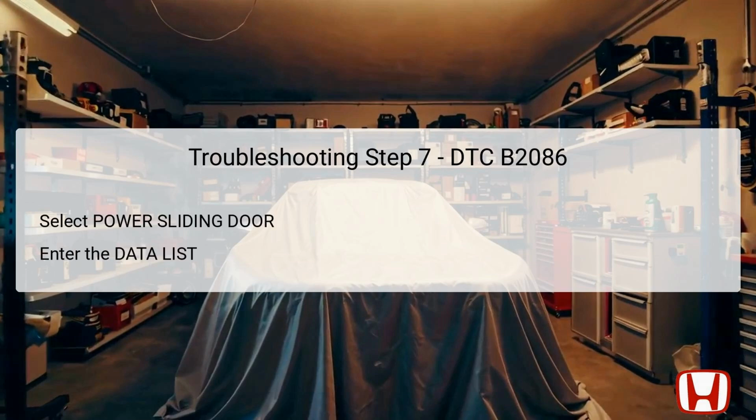In this seventh step, you will select the power sliding door function from the HDS and navigate to view the data list. This function is helpful for monitoring real-time data from the sliding door system and allows technicians to analyze how the system is functioning.